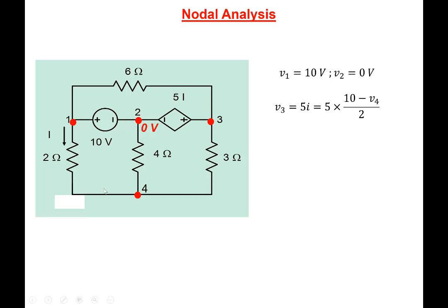So temporarily we are assigning, let's say this is 0. And thereby, we know V1, we know V2, and we know V3 also. We have an expression, so we can write KCL at node 4 now. Node 4 for us is unknown right now, because once we have removed this and made this 0, so KCL at node 4.